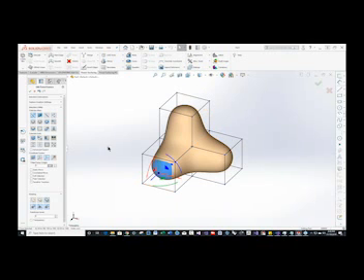Well, let's pick this one, and I can change the weighting on the edges. So for example, at 0 weight, it's just standard Catmull-Clark subdivision, and Catmull-Clark has a technique for adding weighting to vertices, and we use the same mathematics behind that. So you can see as I increase the weight, I have rounded this off almost like a fillet.